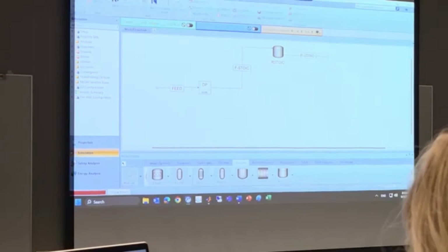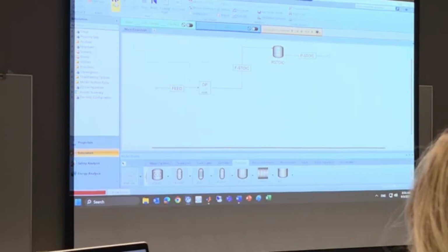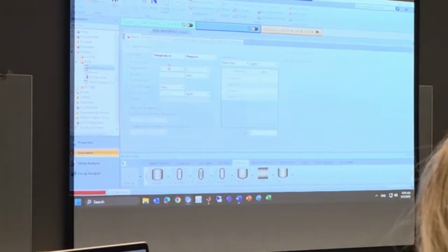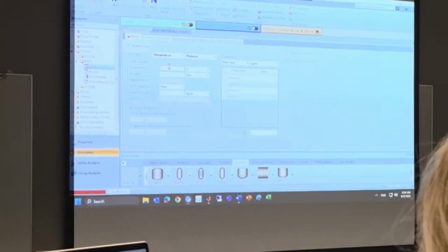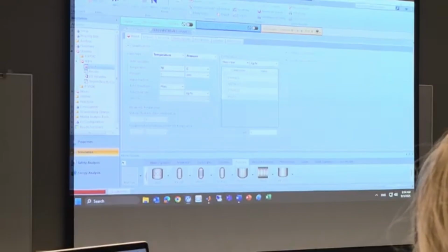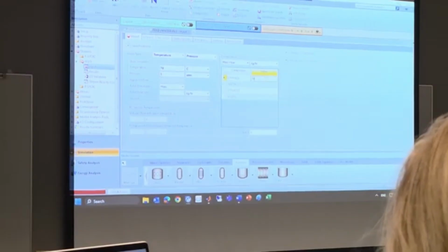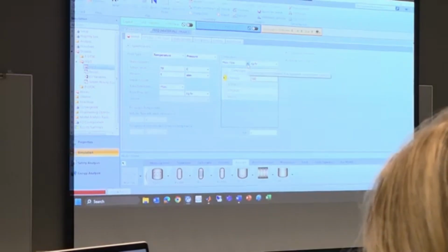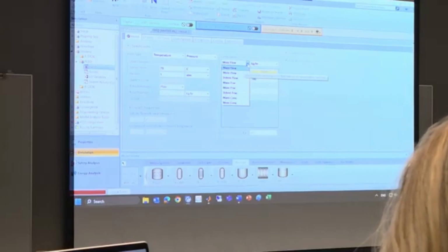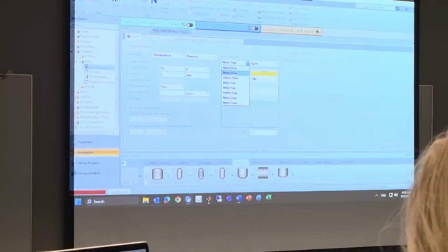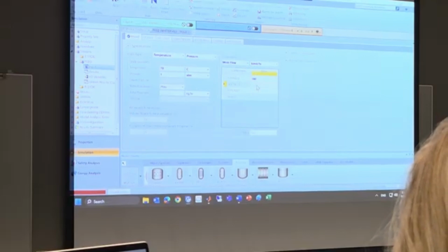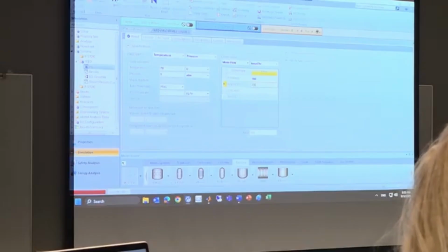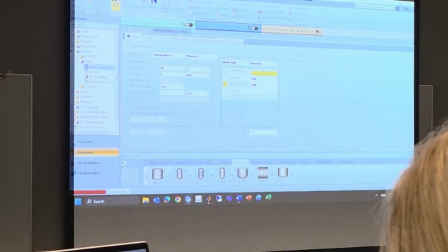Don't know what to do? Maybe I can click the next button. Okay. Now the temperature, pressure, and mole flow are all given. Temperature is 70 degrees Celsius, 1 atm, and ethanol 180 kilomole per hour. The default is kilogram per hour, so I just check the drop down arrow and change to mole flow. So ethanol 180 kilomole per hour, acetic acid 200 kilomole per hour.